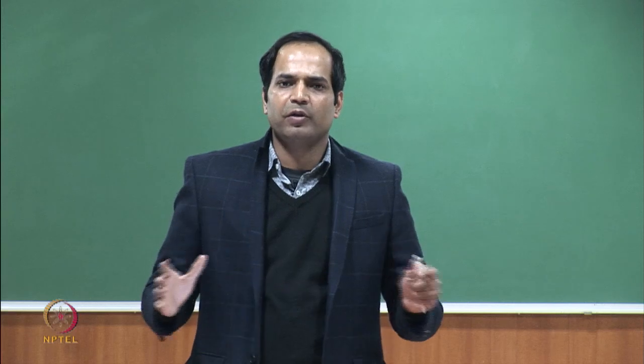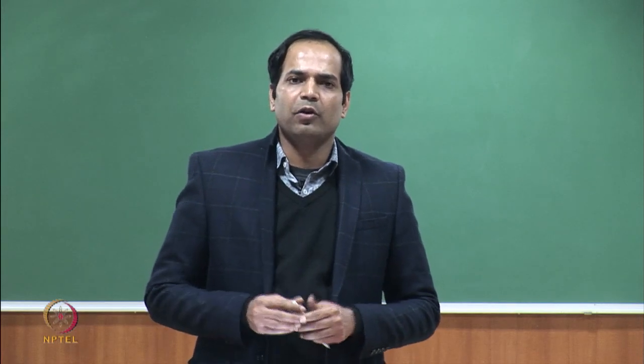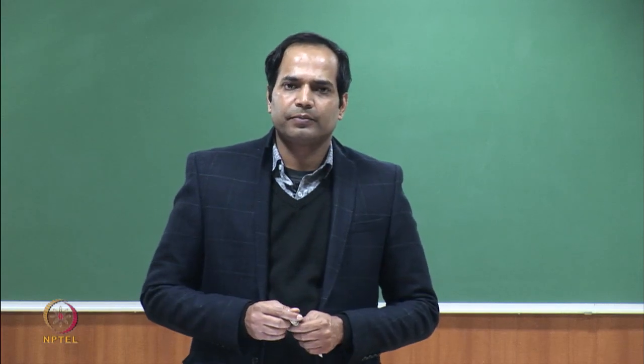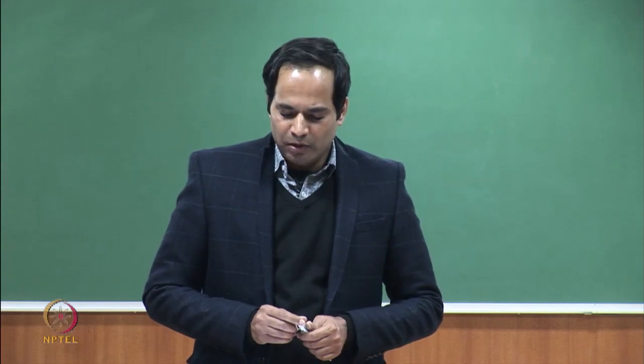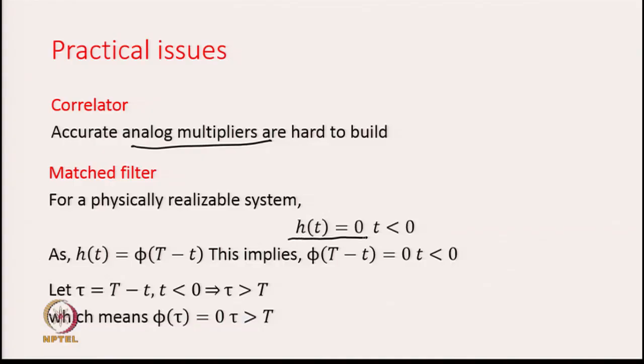If you want to realize a system, it will definitely be a causal system. It will not be able to anticipate which input is going to come in future. One property of a causal system is that its impulse response is 0 for time t less than 0.